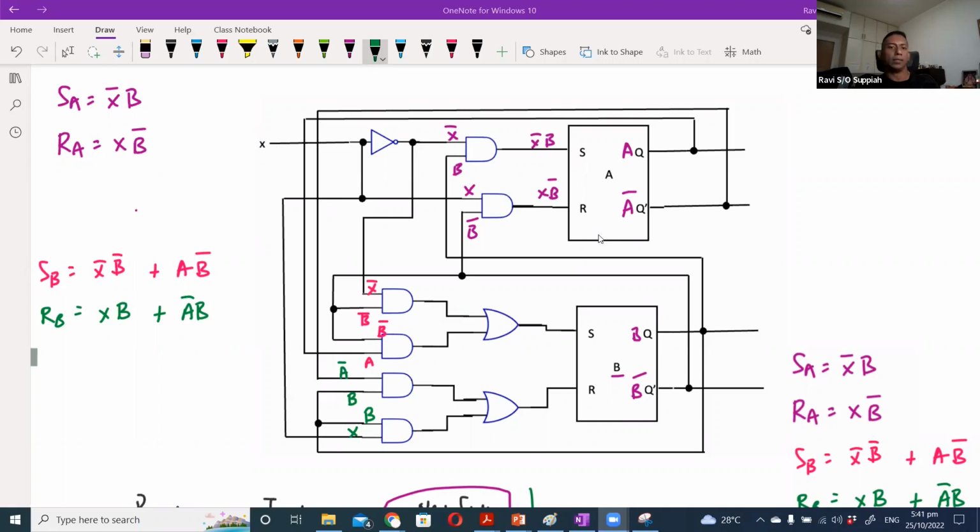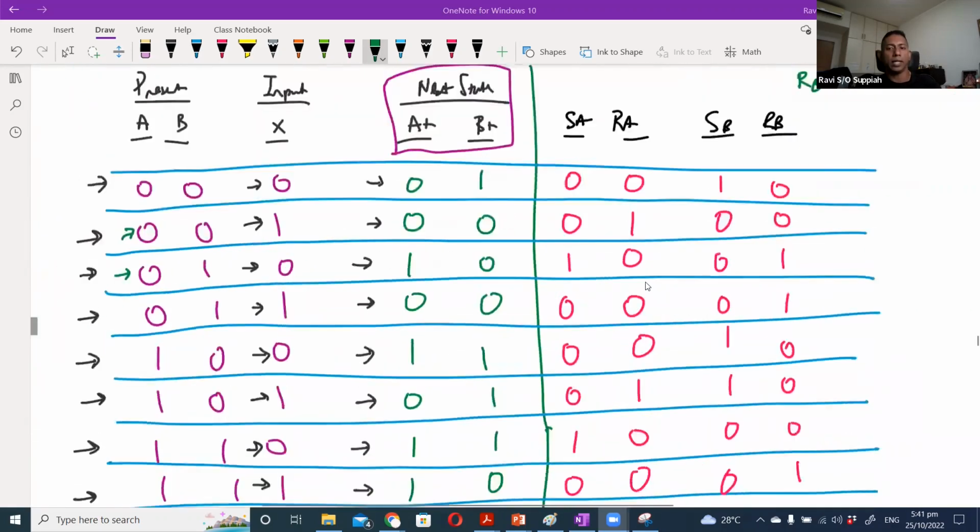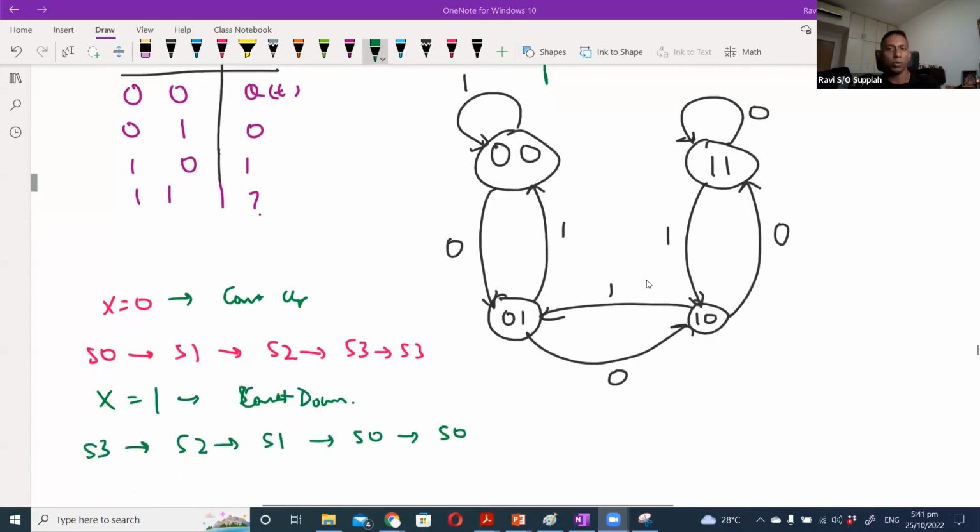So assuming you don't have a reset line, when I first power up the circuit, it could be anywhere. It could be in state 2, or state 3, or state 1. But what we do know is that it doesn't matter, in the sense that the moment the first clock comes in, I will go from the current state to the next state depending on my x value.